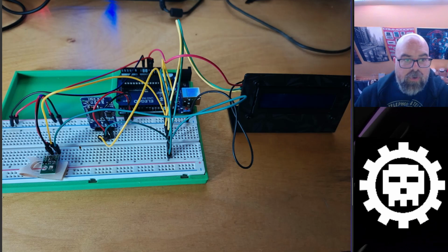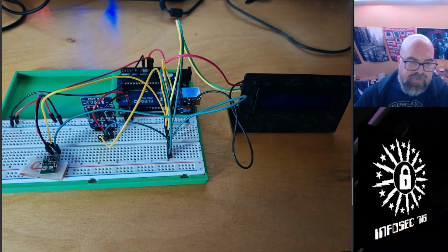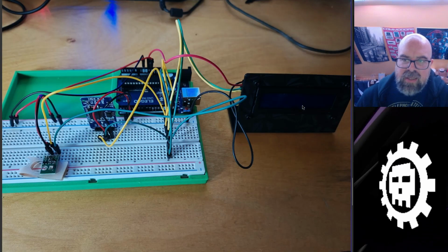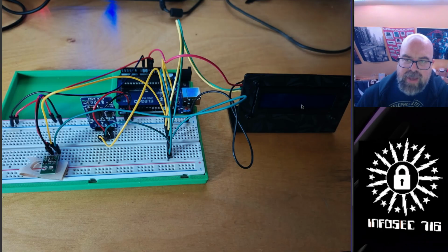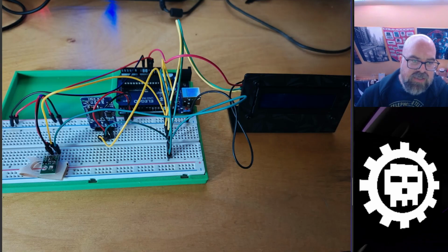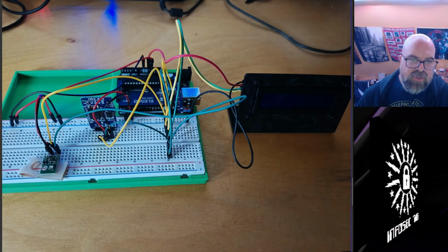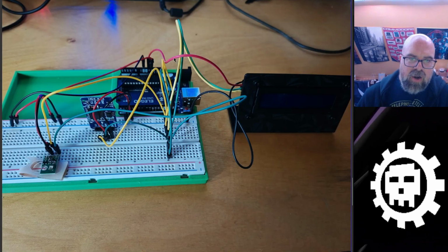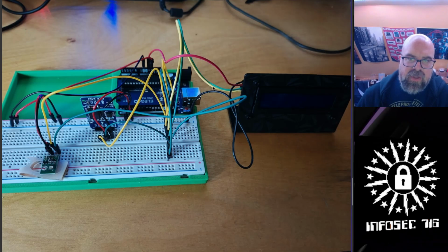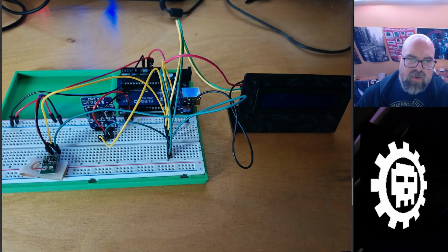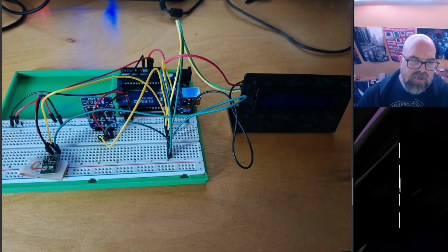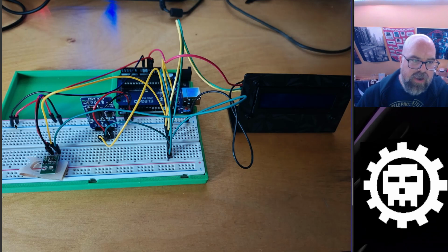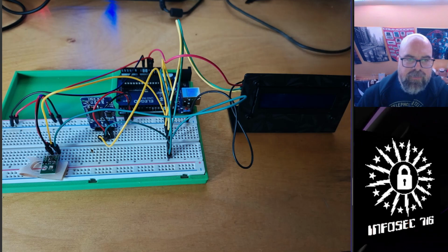So just to go over the connections from before, this is our temperature and humidity sensor. This is our real-time clock. This is our LCD 1602 panel. All three of these are I2C devices, right? So we have a red 5 volt lead coming off of our Arduino here to power the LCD. We have a red 3.3 volt coming off of here to power the power rail on our breadboard. And then we also have a ground wire coming over here to our ground rail on our breadboard.